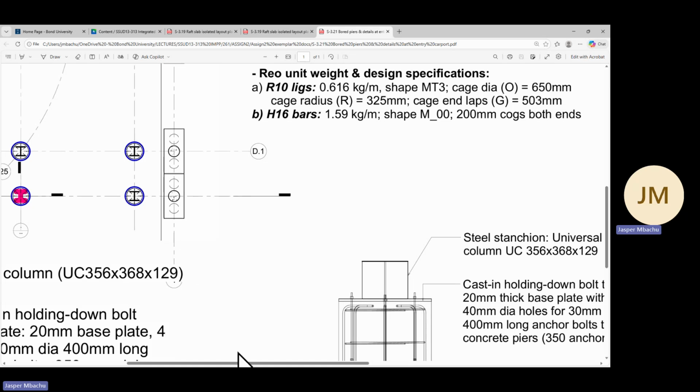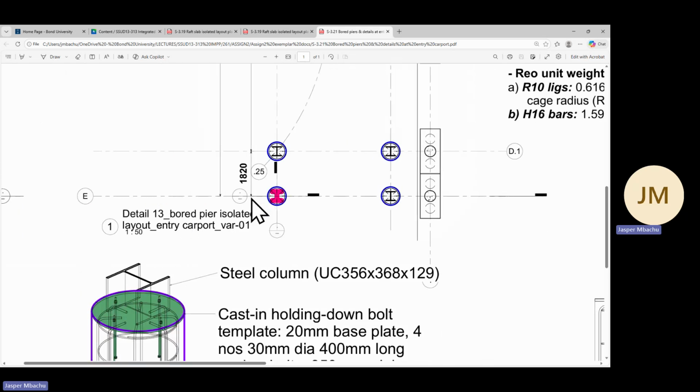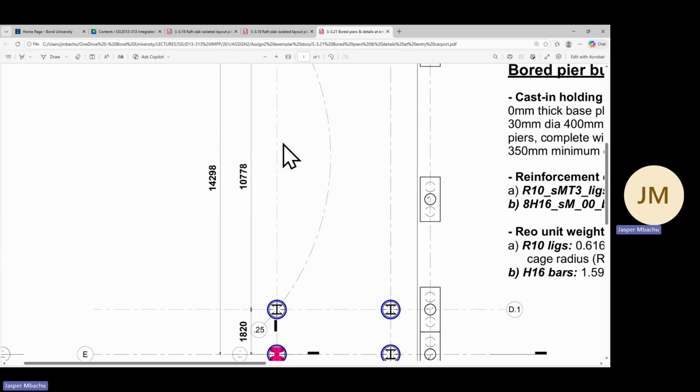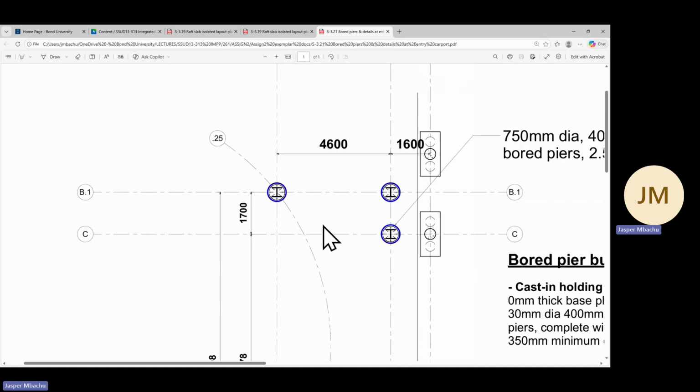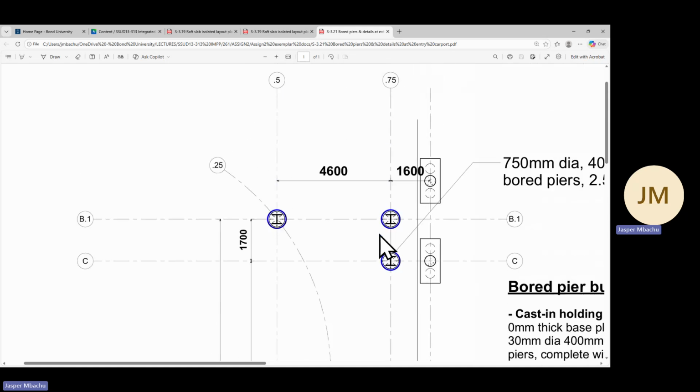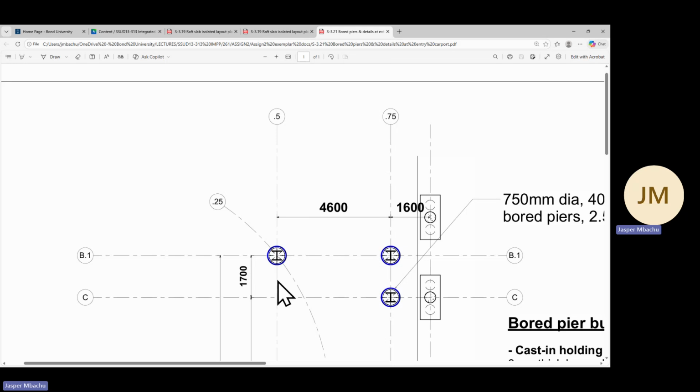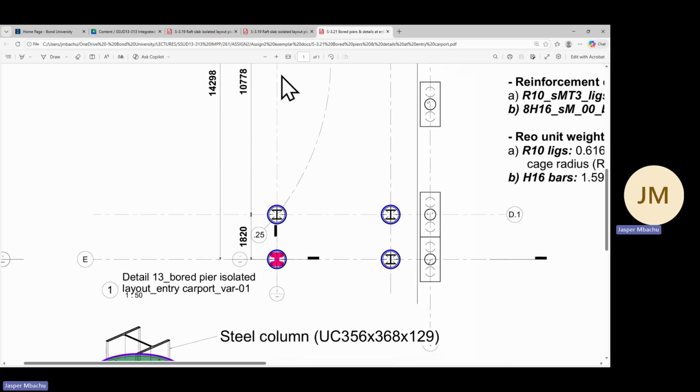And the other thing was to also provide the grid line intervals and then the overall from this side to this side. What I've not done in this drawing, which you can do, is to provide an overall from here to here. So provide an overall here. So we have individual, and then we have the overall. You don't need to do it here because of the one at the top. And make sure that the grid lines are showing.